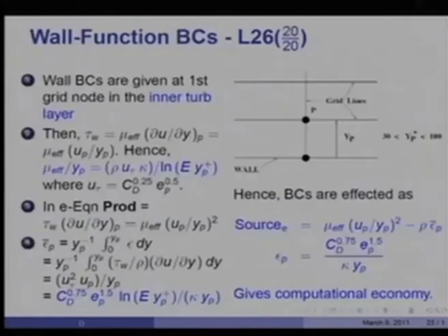Now, of course, these equations apply, as I said, to the high turbulent Reynolds number region, which means beyond the transitional layer, and therefore, in a practical flow, the layer up to the transitional layer must be somehow captured in a computation. That is done as I have shown here.